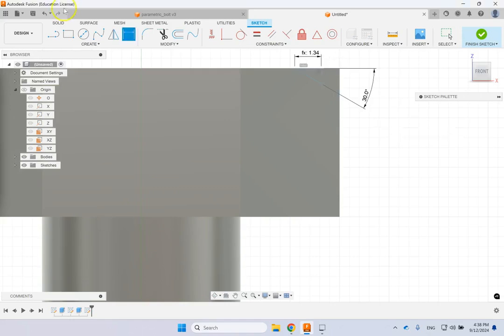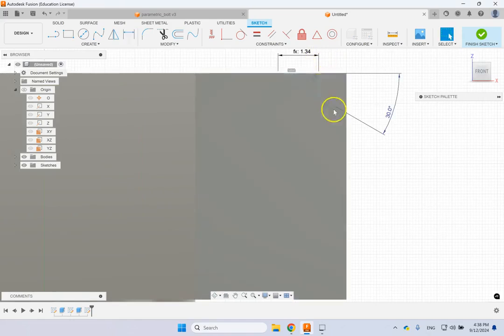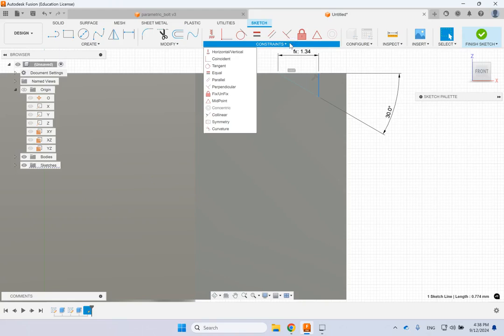Enter. Now here you see that the profile is good, but remember this edge and this one should be coincident, right? And here I try to grab that line and then this one, and you see it does not necessarily allow me to do that and then force them to be collinear, right?